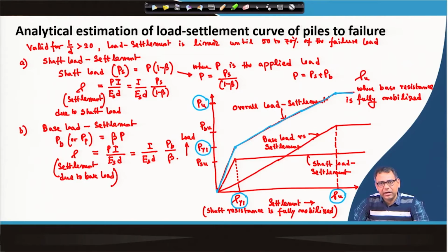So, that will not create any effect on the pile material settlement, because at that time soil settlement is going on. As I mentioned, when the soil settlement stops, then the pile material settlement, or pile settlement, will start. That means the tip resistance during the friction resistance mobilization will not create any effect on the pile material settlement. So, we have to subtract that component from the total base load, so that we can determine the actual load contribution to the pile material settlement.